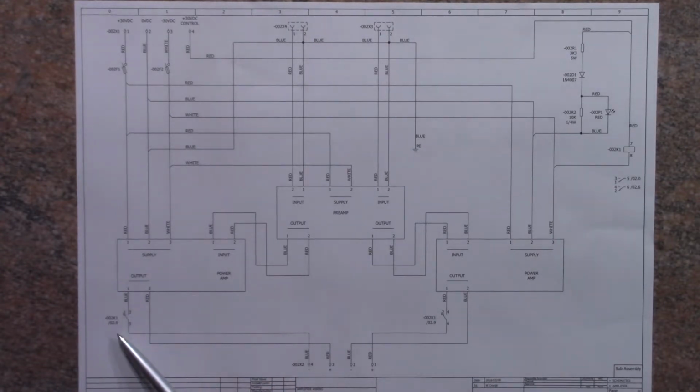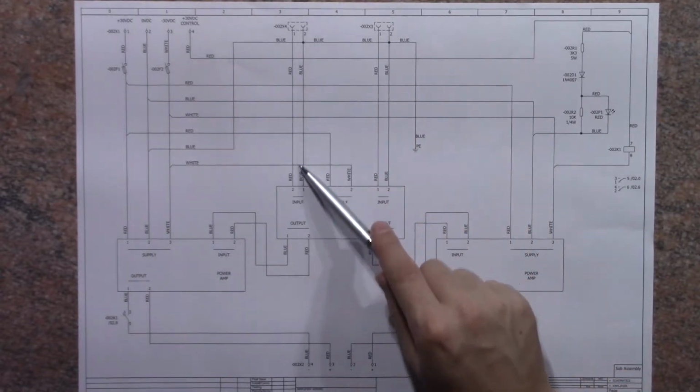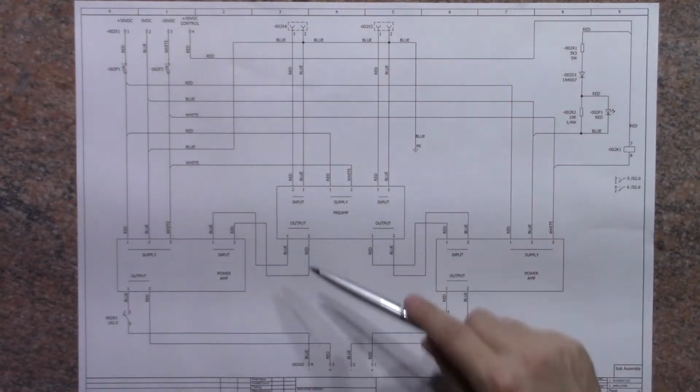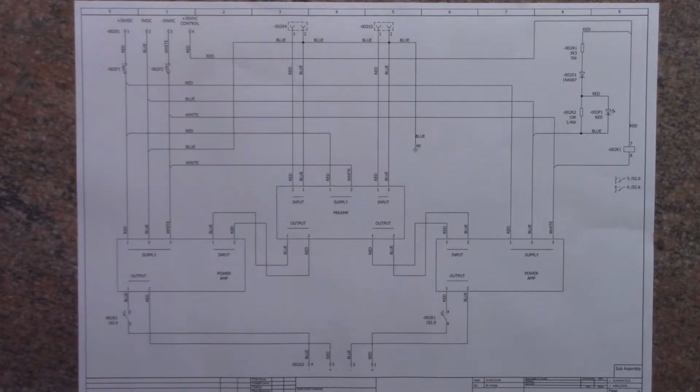through a relay. This is the relay that stops the popping sound on your speakers when you switch on and off. So when you plug the amplifier in, this relay is open. After about 3 seconds it will close, and when you remove the power or the main supply, this relay will drop out immediately. And then also the output of this amplifier is inverted. So we have an inverted input signal and an inverted output signal, which means the whole channel is still in phase, but the electronics inside works out of phase.